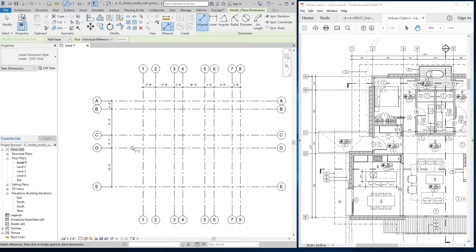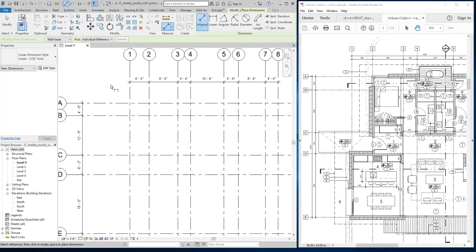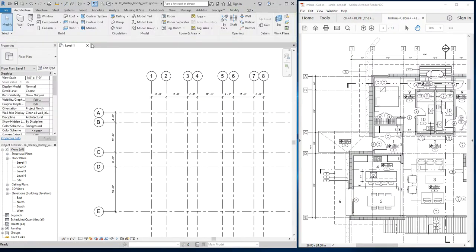You change one and then match property. Yeah, so you don't have to redraw it? Oh, what do you mean? Sorry. The old drawing, take a grid line, one of those grid lines or plane line and change the grid line in the match property. I don't think that'll work because they're two different types. You have to match properties to identical objects. Okay. Yeah, I don't think it'll change one to the other.